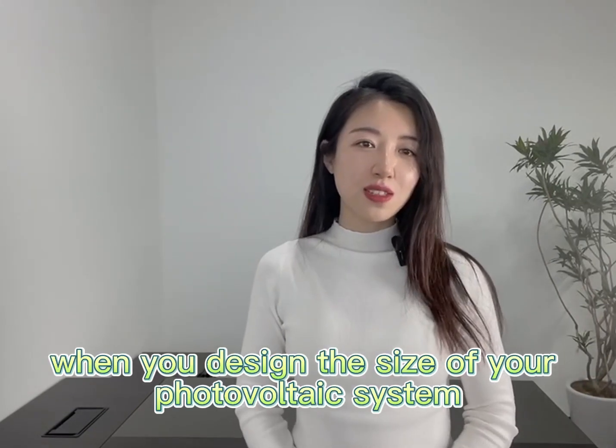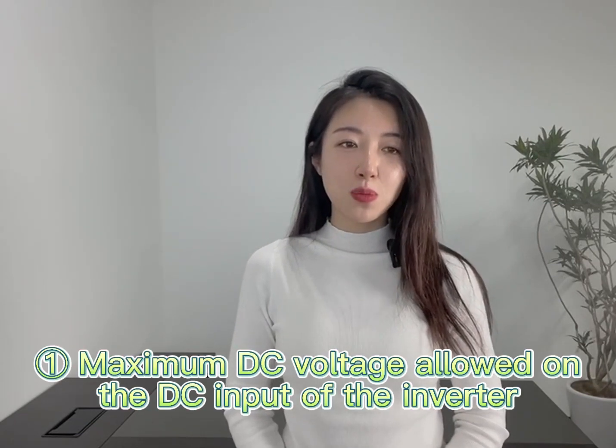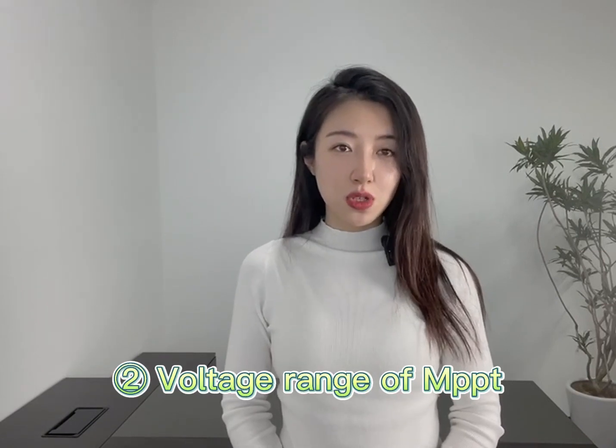When you decide the size of your photovoltaic system, that is, calculating the number of modules in series in your home, 2 voltage values must be taken into account. 1. Maximum DC voltage allowed on the DC input of the inverter. 2. Voltage range of MPPT. So how do the two parameters work together? Taking Australia as an example, we need to consider the DC input voltage, and the following points should be noted.